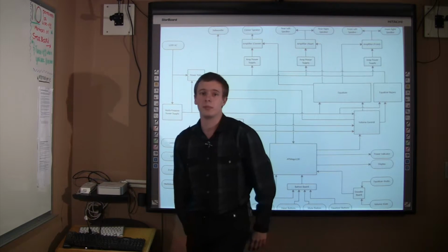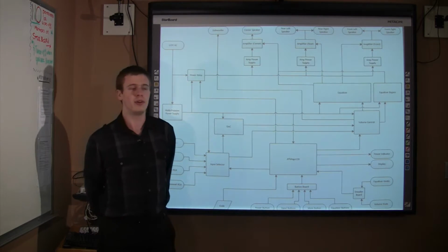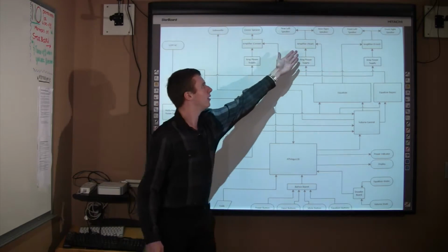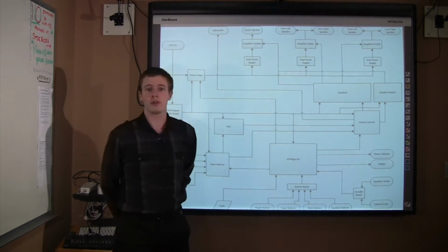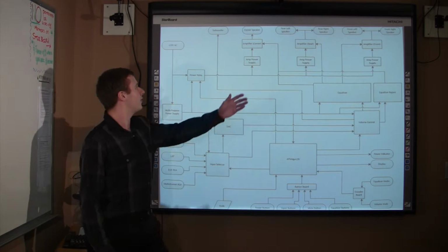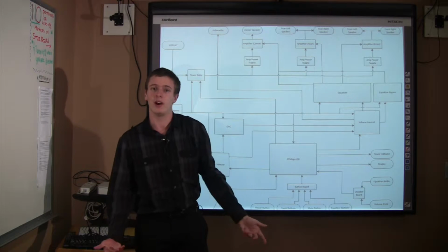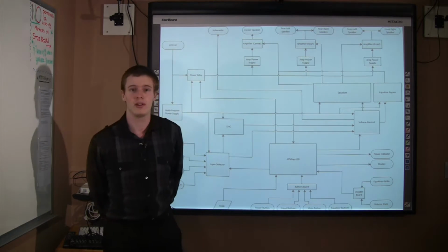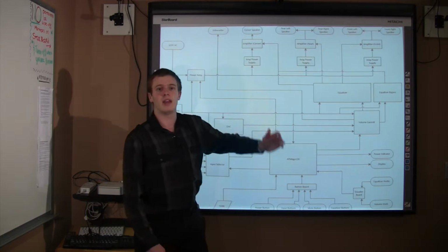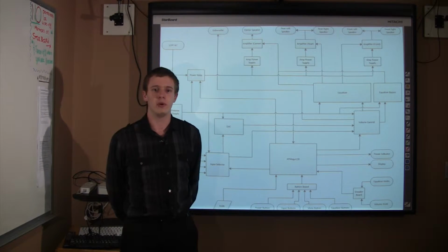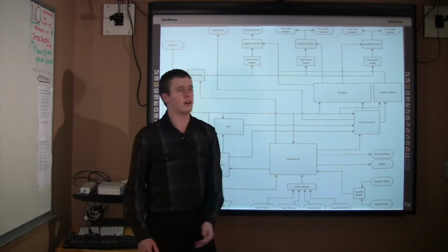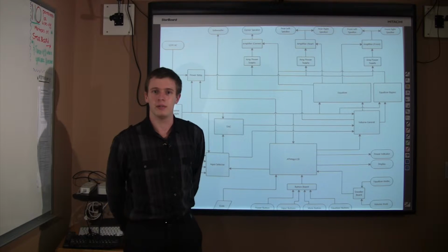These amplifier power supplies will supply 27 volts and up to 5 amps to our three amplifiers. Our amplifiers are Shure Electronics Class D stereo amplifiers. The output of the amplifiers is quite obviously our amplified audio, which is played over the speakers. The subwoofer has its own built-in amplifier, so we forward unamplified audio to it. The inputs of the amplifiers are simply our unamplified audio.